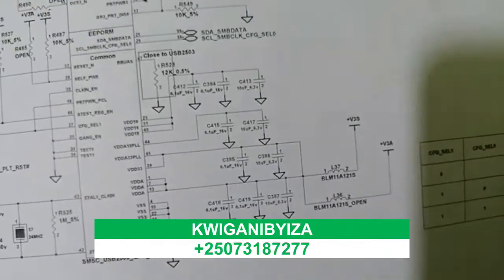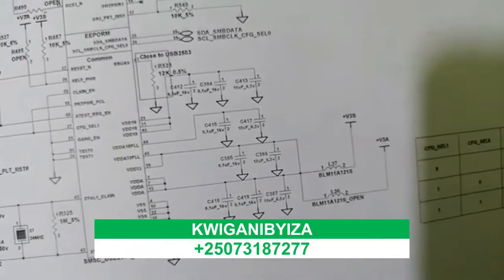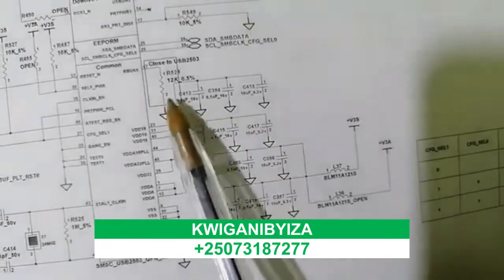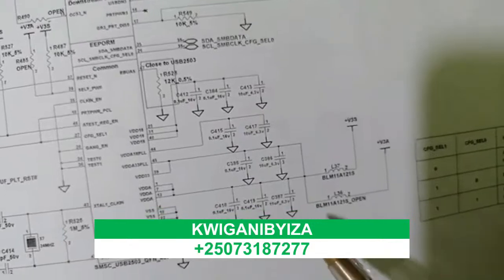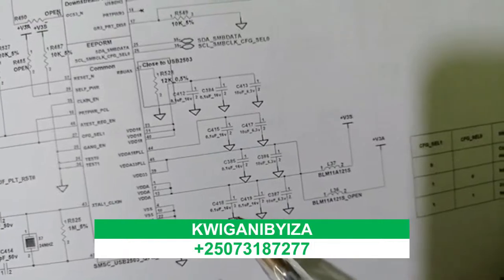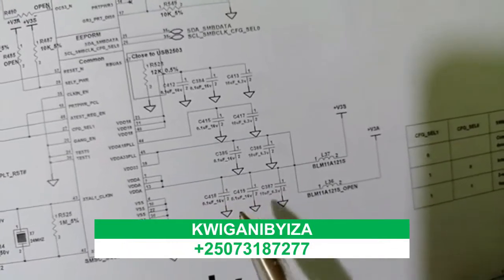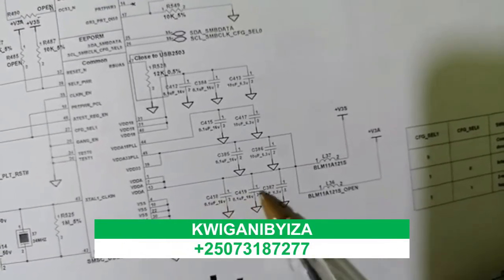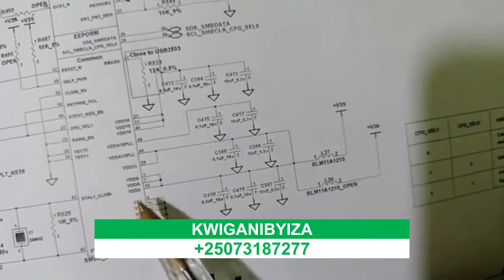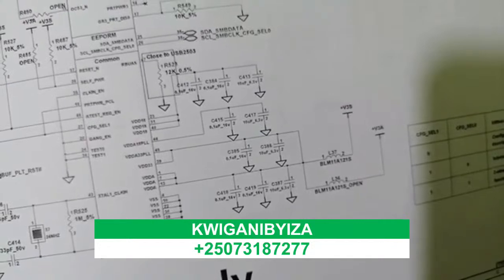As I told you before in the previous videos, this is basically an IC. Next to each IC, you will find many ceramic capacitors, as you can see over here. The ceramic capacitors are always connected to the ground on one side and connected to the IC on the other side. That's why if you find, for example, that these 3 ceramic capacitors are shorted, it means the IC is shorted. So this is the second method that we use to check the serviceability of an IC.